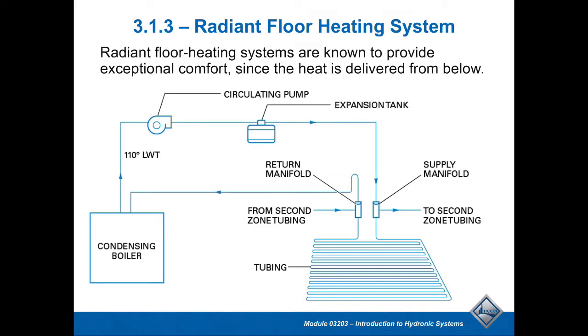There's another system that we utilize a lot, and if you're dealing with any new construction, there's a very good chance that somebody might be using a radiant floor heating system. And the purpose of that is the fact that now I can use probably some PEX tubing embedded in the concrete floor, and I can take advantage of maybe a condensing environment potentially that would allow me to have very low water temps, achieve very high efficiencies. And again, those are typically done, we'll set up manifold systems with a supply and a return manifold and pump it through the system accordingly.